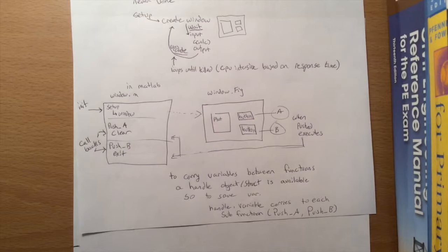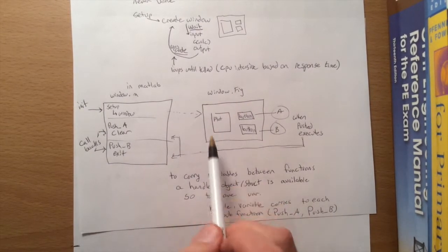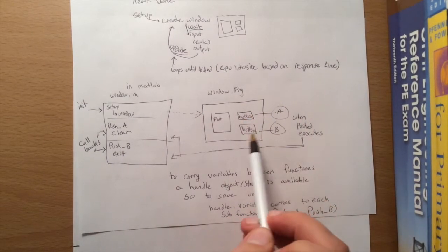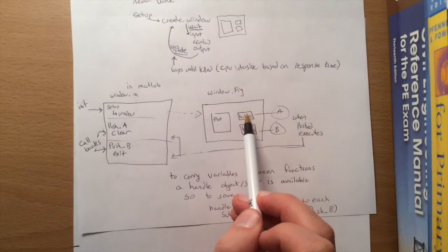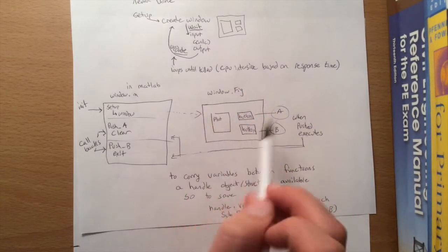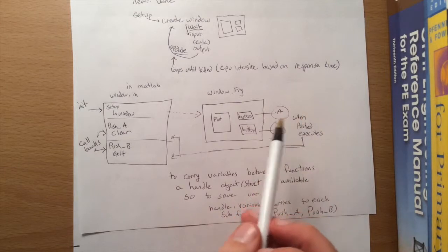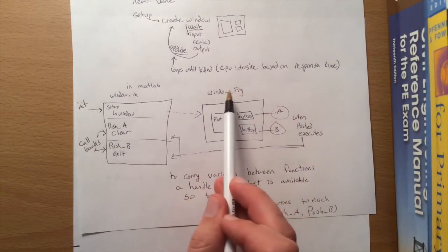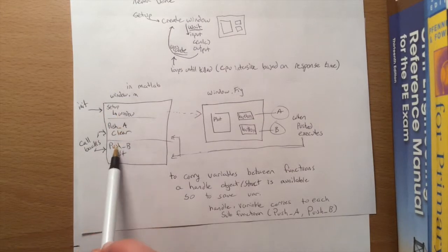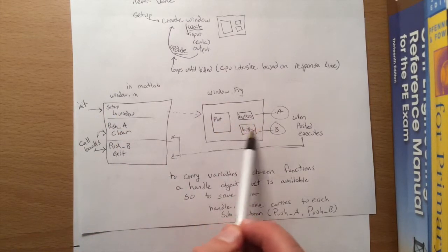So moving forward, the GUIDE toolbox in MATLAB generates a window figure. In GUIDE, you're able to click buttons and drag features for your window, such as a plot box or command buttons, over onto the side and construct this graphical user environment. Once you save your figure window, GUIDE will generate a MATLAB file with functions for each one of the features you've put into the box.